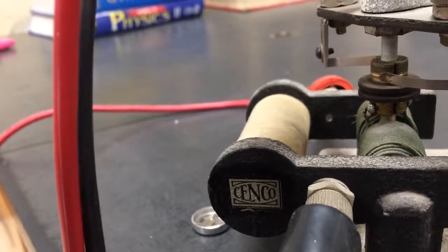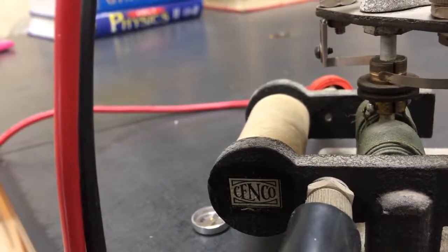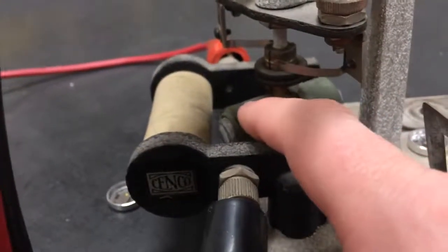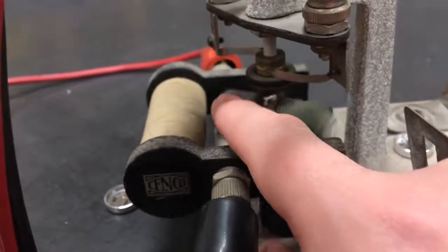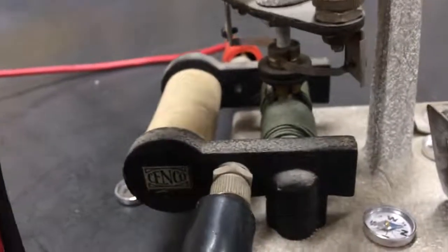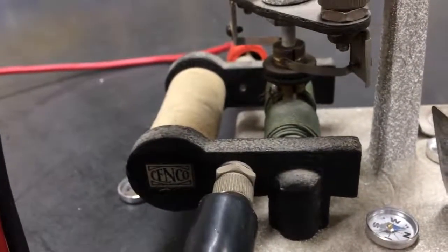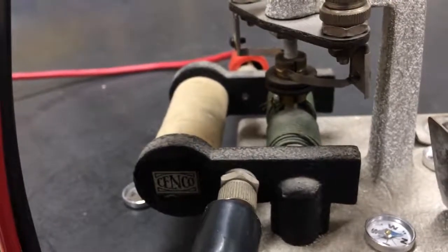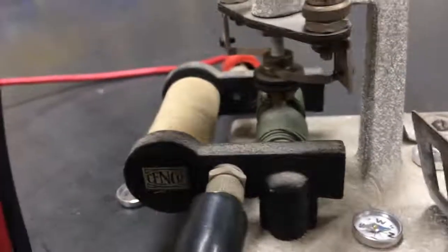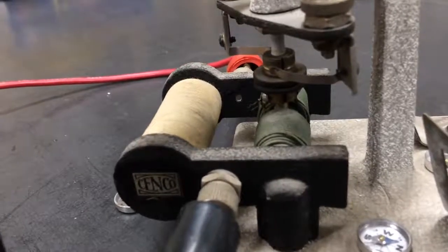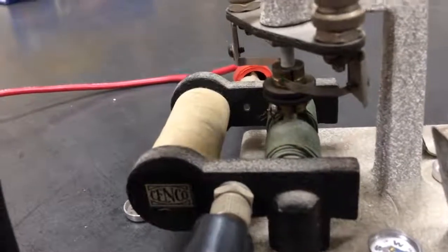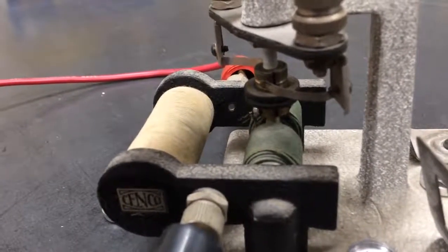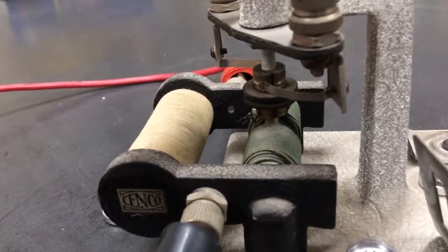And that means that we're always getting pushed in the right direction because the time after we've gone around once, it flips, current reverses, so now it continues to push in the direction we want. So it's on all the time instead of half the time, like the previous motor. With an AC motor, you don't have to because the current automatically reverses, so an AC motor is much simpler. But there's lots of applications where we need a battery, which is portable, to power an electric motor, and this is how it works. Not surprisingly, this brush mechanism can wear out after time, and that's why DC motors eventually have to be replaced.